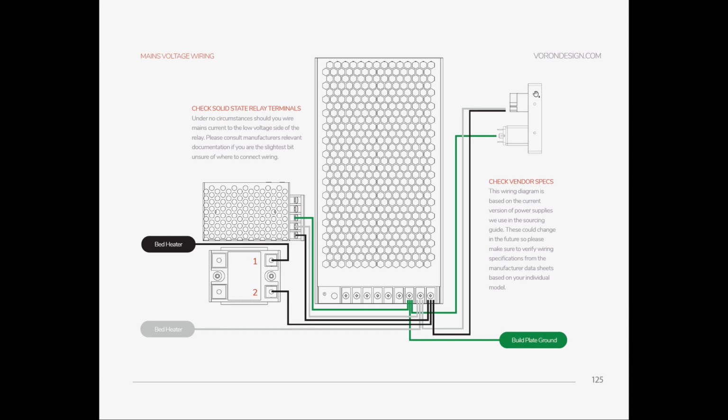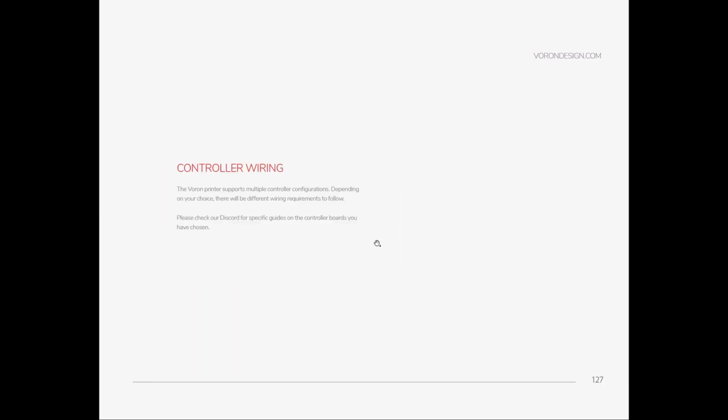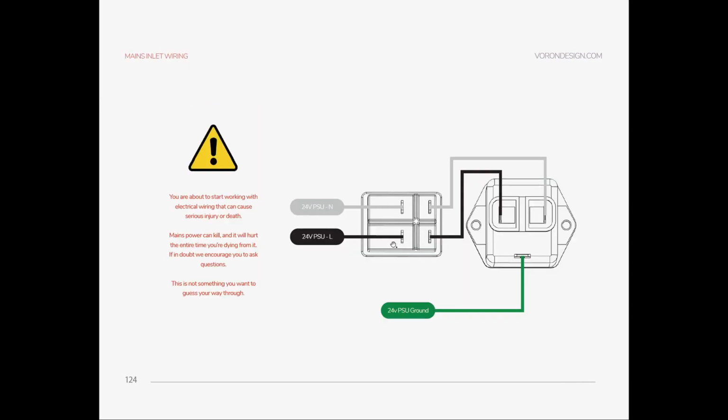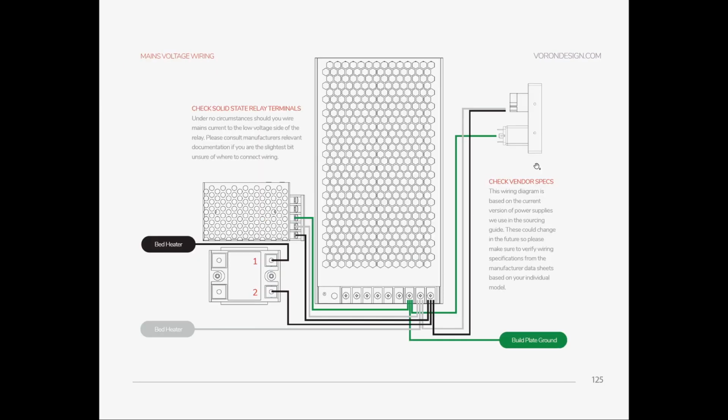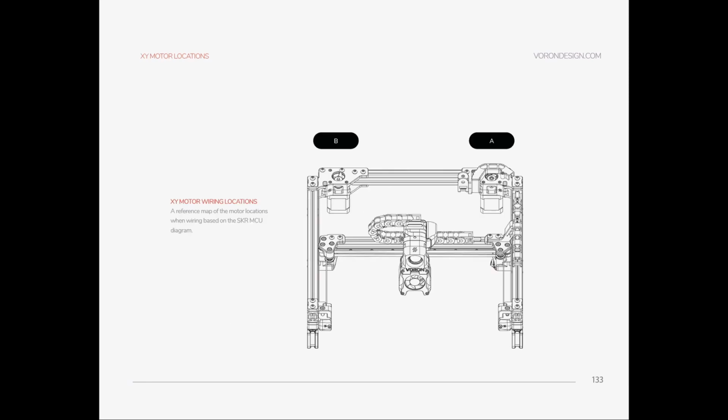But imagine that if you ran all the wire at once and something is not working. It's okay, it's again diagnosable, but the other way is more convenient, less time consuming, and more safe, is what I'm trying to say. Just follow these diagrams. It's not hard, just follow the wires, and that's all. In here, if you are not using a Wago or terminal, you are using something like a terminal. So your mains comes in here and it's distributed from here.